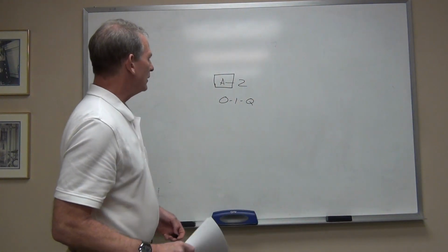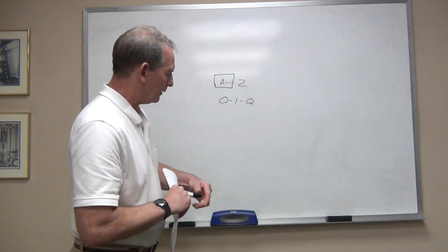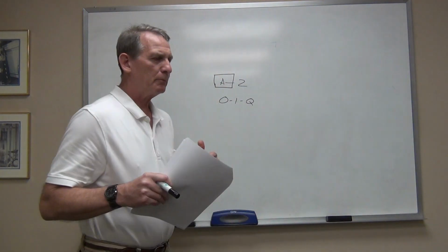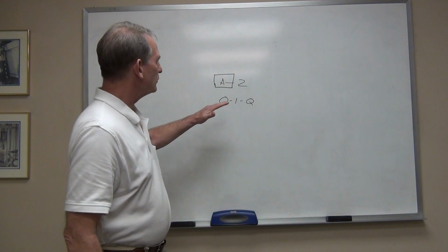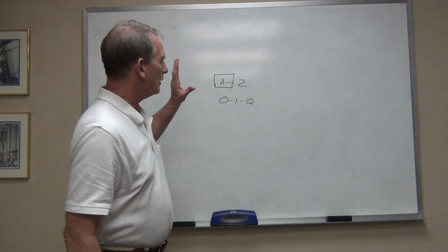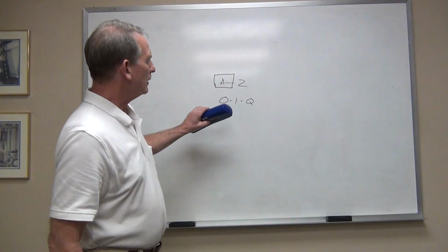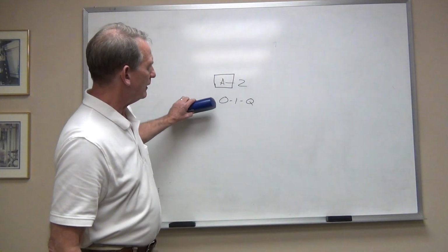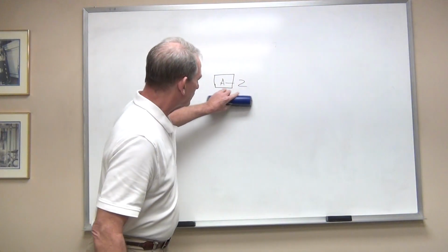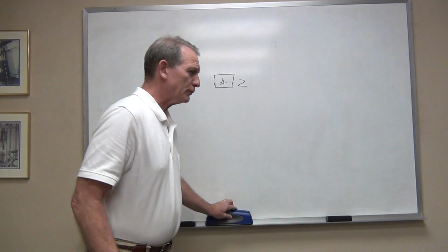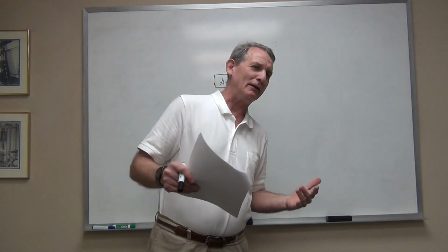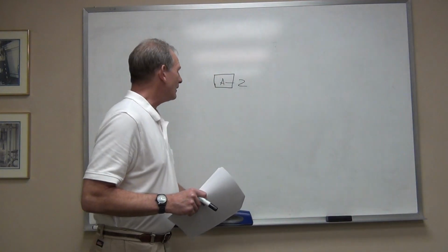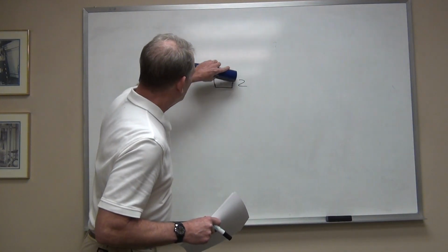There might be another one in there that they don't use, just to prevent confusion between numbers and letters. So pretty consistently in revisions and in datum callouts, we don't use those letters. Okay, so you've got A through Z, that's 26, minus those 3. You have 23 datum notations available to you.